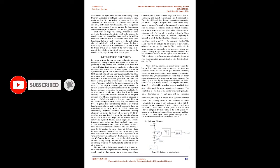Here are two types of fading: small-scale and large-scale fading. Profound and rapid amplitude fluctuations characterize small-scale fades as the mobile moves over distances of just a few wavelengths. Multiple reflections from the mobile environment cause these fades. Small-scale fading typically results in a Rayleigh fading distribution of signal strength over small distances. The large-scale fading is mainly due to shading, due to variation in both the terrain profile and the nature of the surroundings. In the case of deep shadows, the signal strength received on the mobile can drop significantly below the free space. 3. Introduction to diversity.